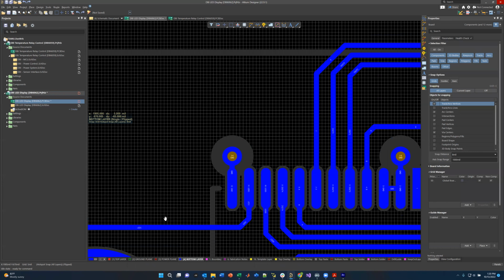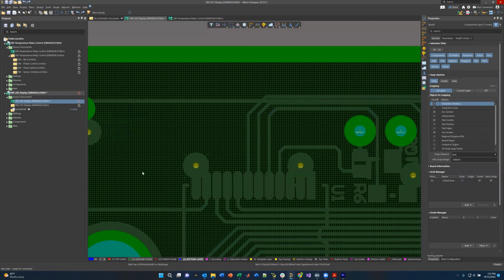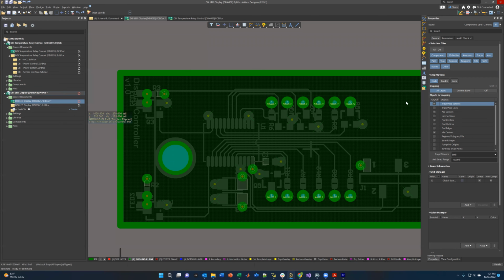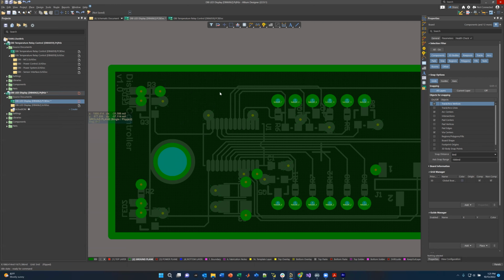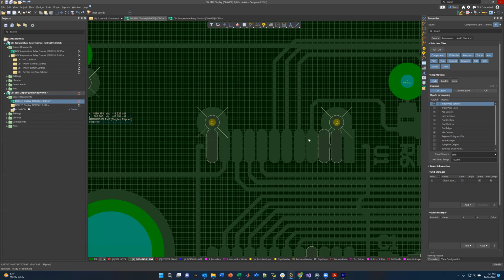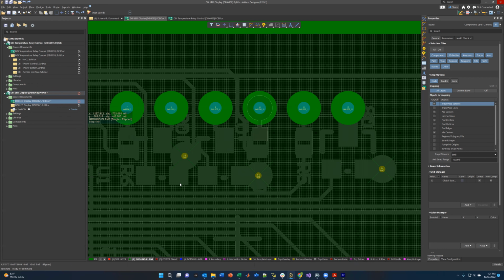Sometimes you don't want that, because anything that's not ground, you don't want connected to it, like the LED 5-7 net here. We don't want ground connected to that. So if we look at the ground layer, all that you see here that's not green is all copper. It's kind of a negative image. If you notice, there's no green here. So basically, this via is directly connected to the copper. There are different connection styles, but I use direct connect for this to get maximum copper connection. And if you notice, on these signals for these LEDs, which go through the board, they are completely isolated, so the ground layer will not connect to that.